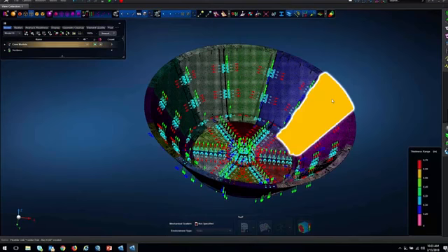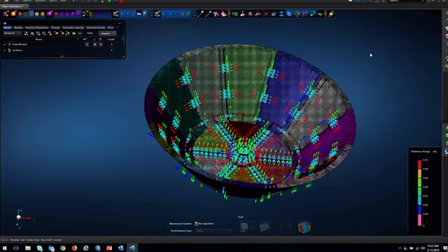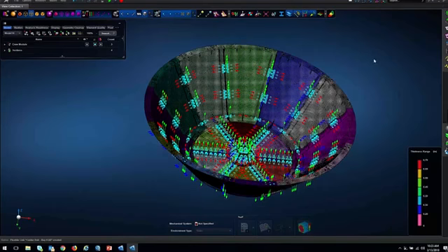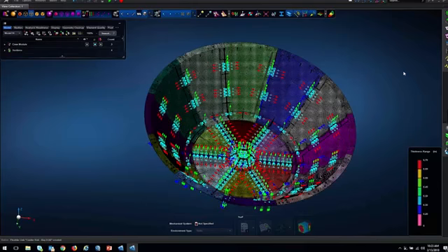And we created the flexible bolts in this case, and the bolt properties are automatically extracted based on the hole diameter. Now let's say you did a baseline analysis, and you could potentially use your edge and vertex drag to modify the hole diameter, and thereby with the generative behavior, the mesh gets updated, and simultaneously, because of the hole diameter, the property of the bolt gets updated, and then the new model is just about ready to run the simulation. So now basically with these three scripts, this model is meshed and assembled.